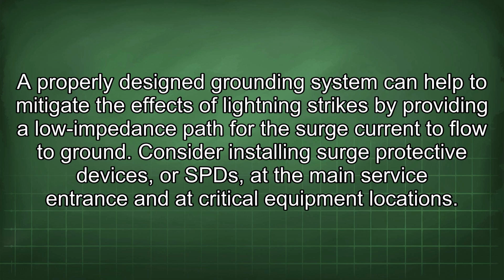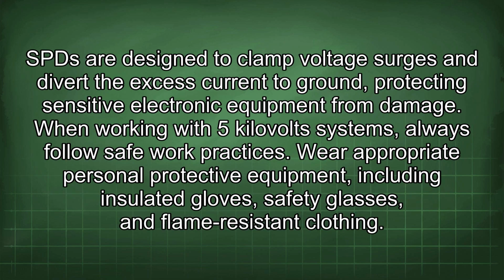Consider installing surge protective devices, or SPDs, at the main service entrance and at critical equipment locations. SPDs are designed to clamp voltage surges and divert the excess current to ground, protecting sensitive electronic equipment from damage.